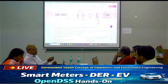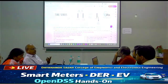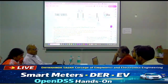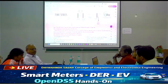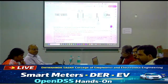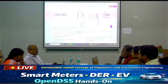So in case of a snapshot, that is the actual load. But when you put it for a daily profile, there is a multiplier. So you have here the actual curve, and this is the multiplier with which you want to multiply. Actual is equal to per unit into base. So this 1000 will be multiplied.